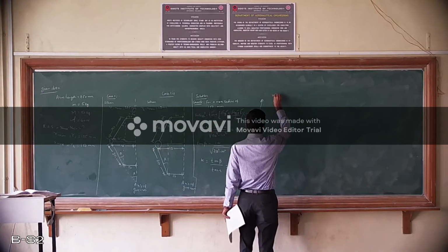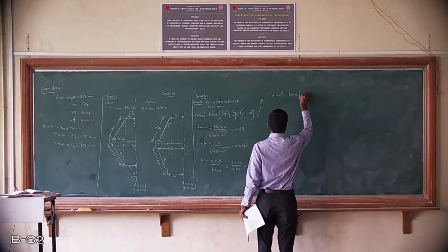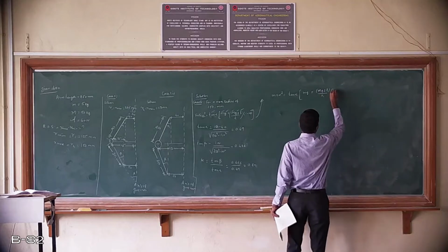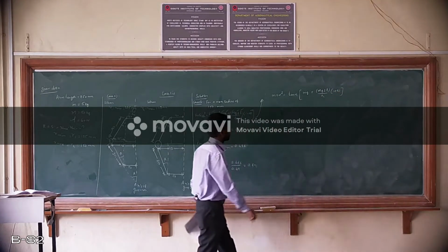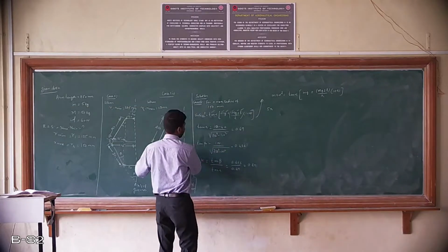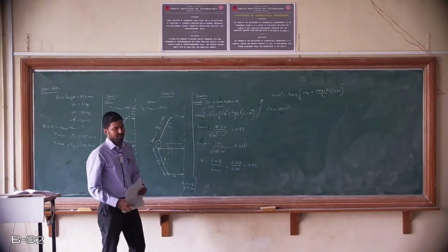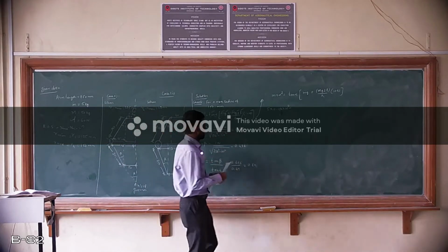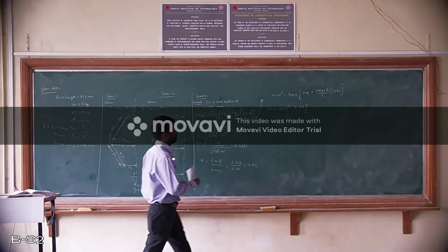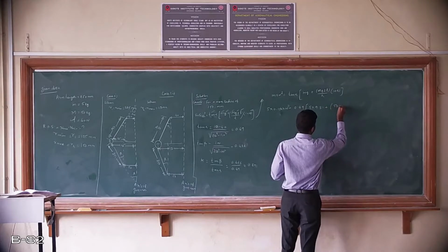So I will write the equation for omega once again, that is mr omega square is equal to tan alpha into bracket mg plus or minus f divided by 2 into bracket 1 plus k. So this is our governing equation. Now substitute all the values into the governing equation. The value of small m is 5. Radius is 150 mm, I will substitute in terms of meters. Omega square is unknown. The value of tan alpha we have calculated as 0.49. The value of small m is 5 kg, and the value of g is 9.81, plus the capital M is 50, times 9.81.